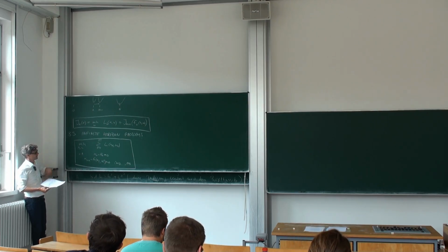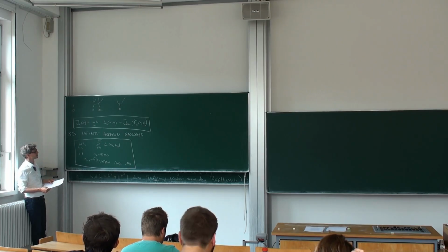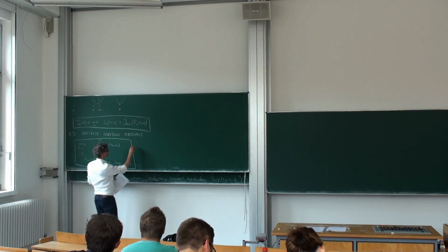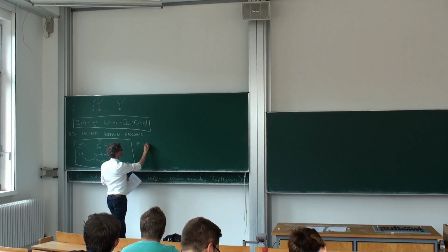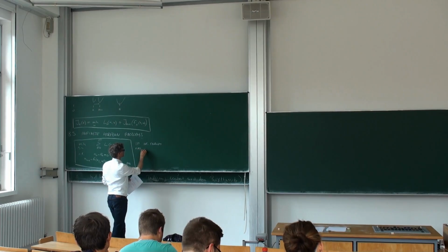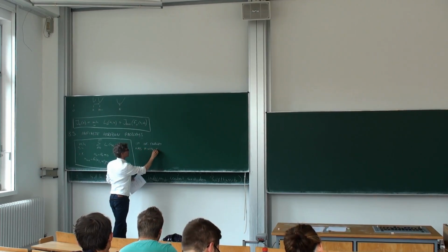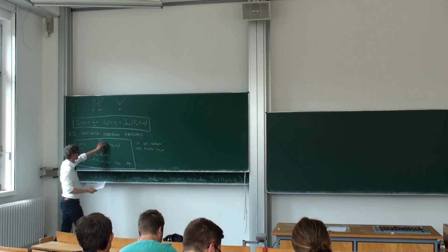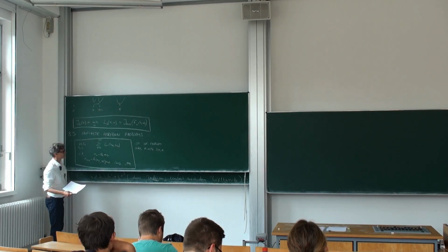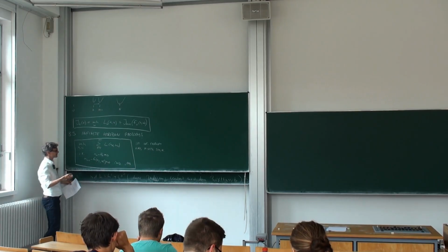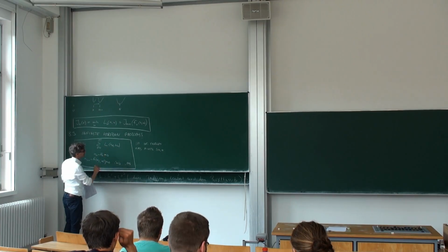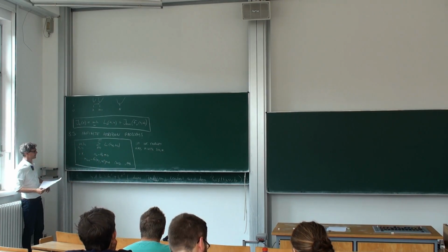The approach that's also computationally possible is that you say, if the infinite horizon problem has finite solutions, which is of course not the case for every problem, just think of a cost which is just 1 at every time point, independent of what you do. This will always sum to infinity, and your optimization problem does not have a finite solution. But in other cases, if you are able to go into a steady state and stay there at 0 cost, then you would have finite solutions.